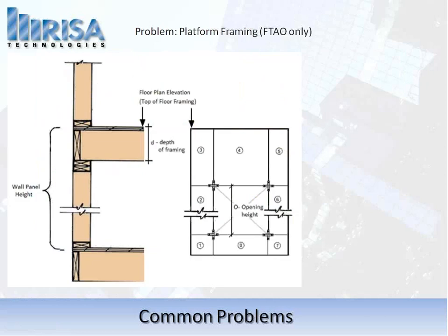Okay, next piece that I see also a lot of times, people have asked about force transfer and openings. What happens if you do platform framing? This kind of came up actually through one of our trainings. A fellow came up and talked to me through this type of problem. And what we've got here is, when you're looking at the left wall, we see that when you are doing platform framing, we're assuming it's going all the way to the top, full height for that framing. But when you do platform framing, you're actually sort of eating up a lot of the area that we would assume for the force transfer around openings.